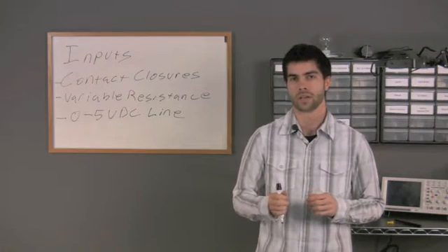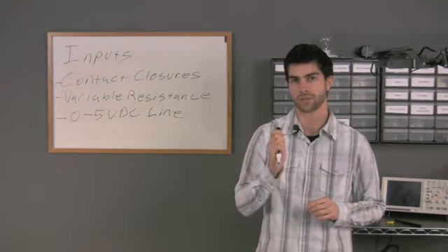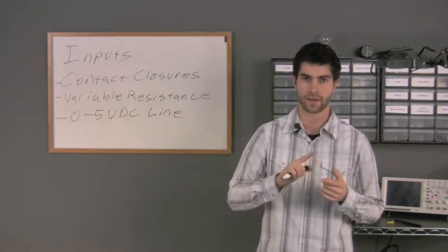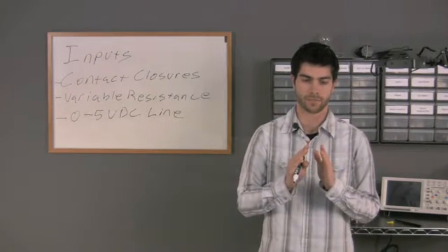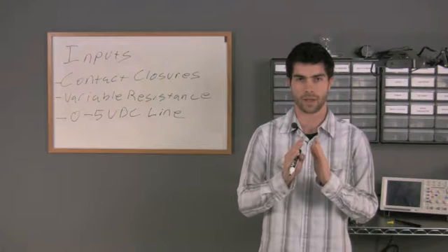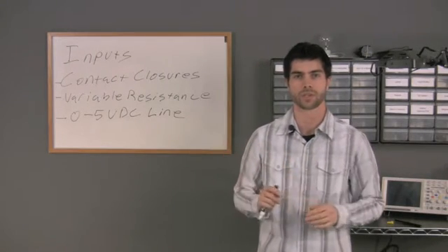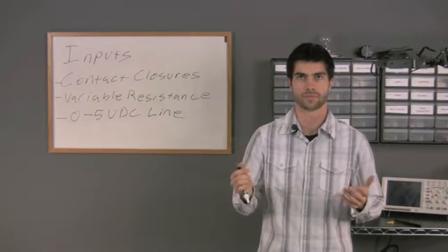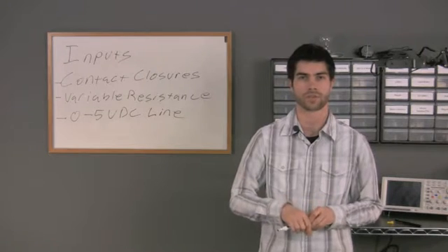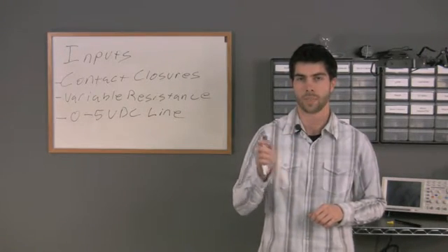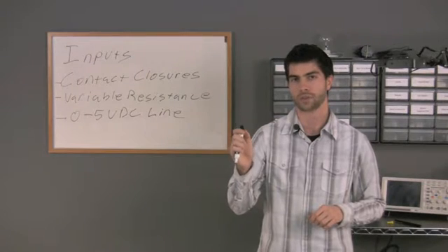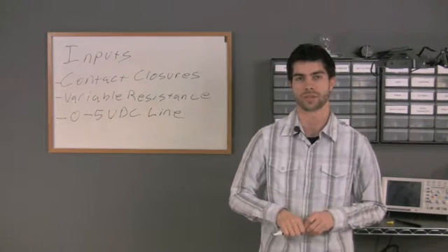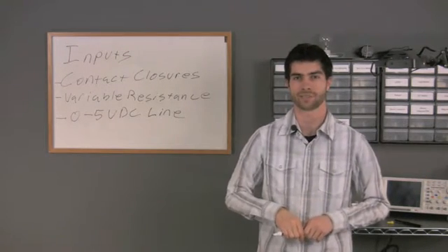Basically what you do is you take 5 volts and you divide it by 255. That's going to give you the number of incremental changes in voltage, the amount of each step in incremental change in the voltage. So you can take whatever that number is, like say 200, it registers 200 on the 0 to 255 scale. You'll take that 200 and multiply it by 5 volts divided by 255, and that would give you what the actual voltage is on that scale. So I won't get into that too much. That's just some lazy talk there.